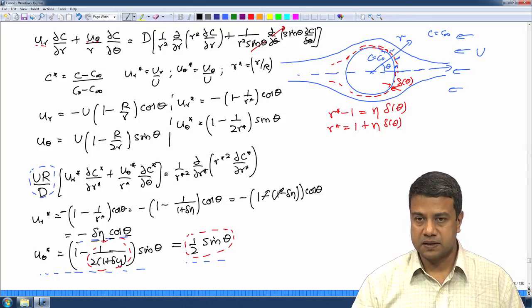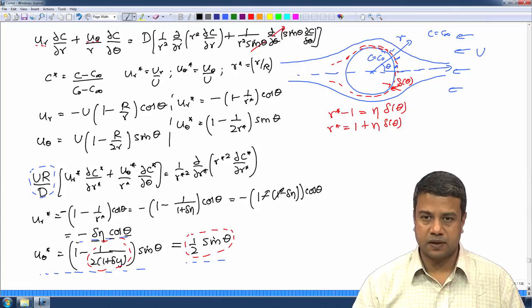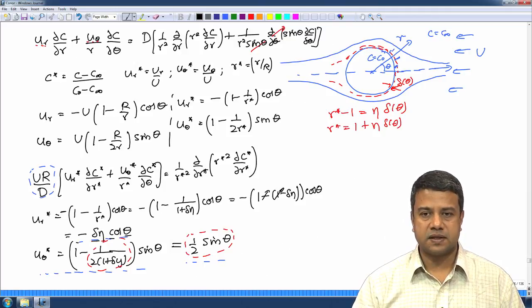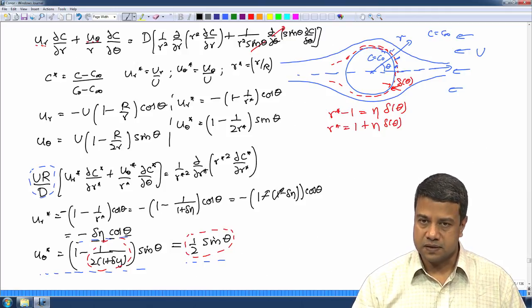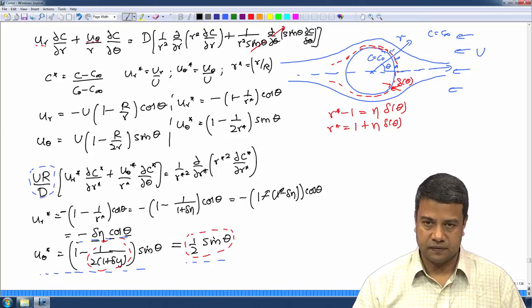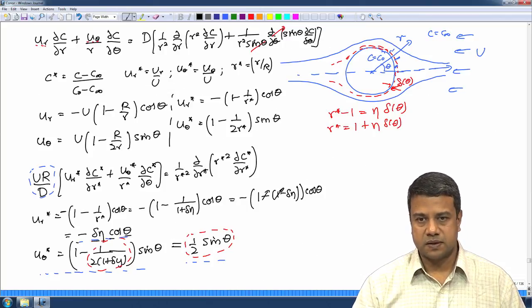For the flow past a surface with a no slip boundary condition at the surface, the boundary layer thickness decreases as Peclet number to the minus 1/3 power. We saw from the convection diffusion equation why that is so. For a surface in which there is a slip boundary condition or a zero shear stress boundary condition, the boundary layer thickness scales as Peclet number to the minus 1/2. From the equations, we saw why that is so.